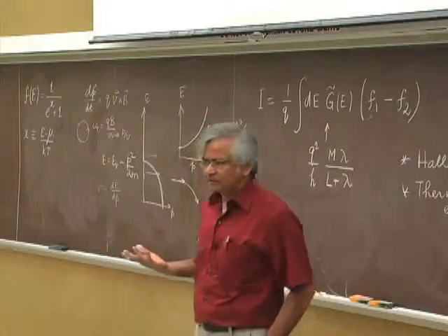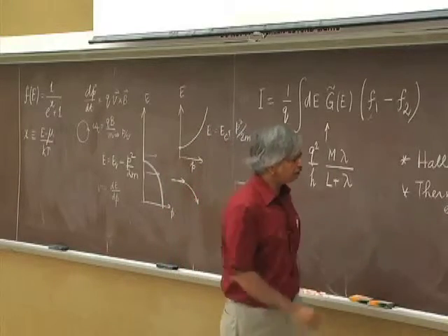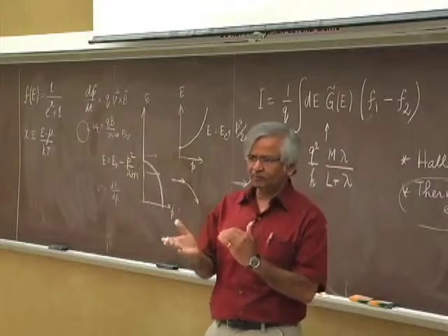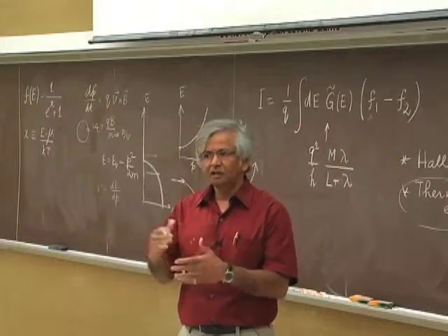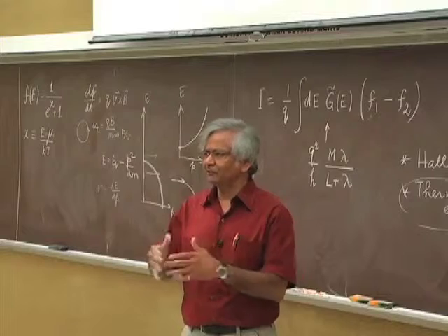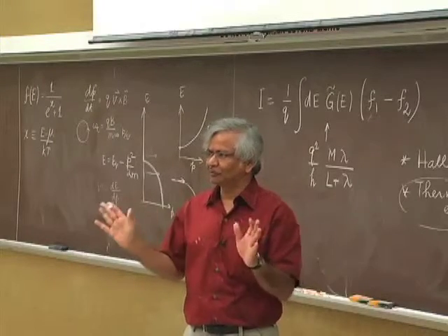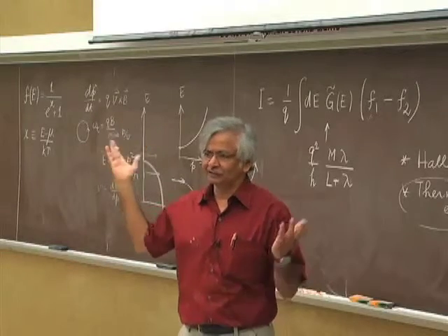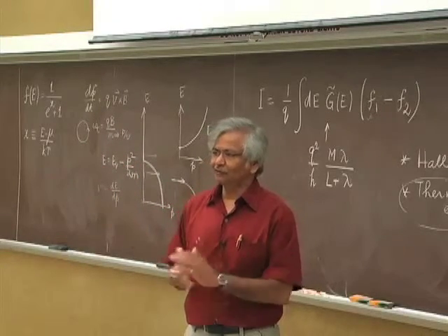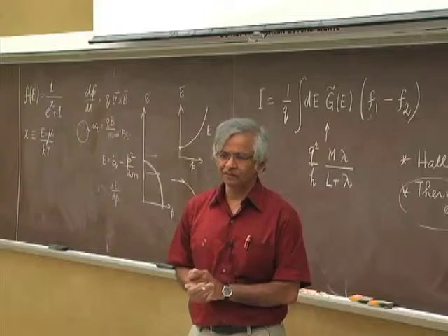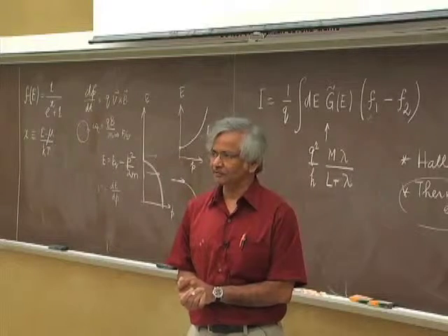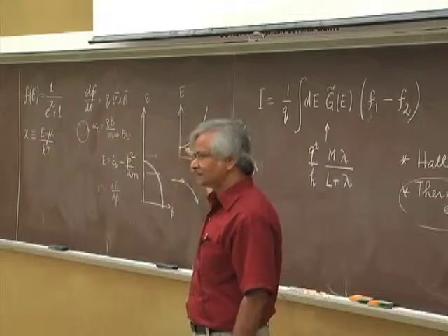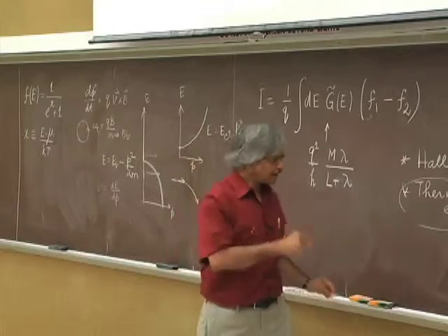Amorphous semiconductors still show a thermoelectric effect that is quite well understood. There are N-type and P-type amorphous materials. But often the Hall effect measurement doesn't agree with thermoelectric measurements at all. An N-type material shows a Hall effect with the wrong sign. It's very hard to understand; there are hundreds of papers trying to understand the Hall effect in amorphous materials. Why? Because there is no E-K relation, no simple picture like this. Anyway, that's an aside.